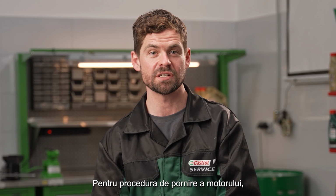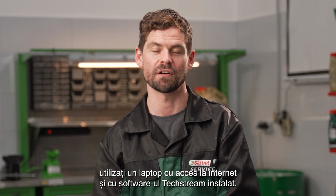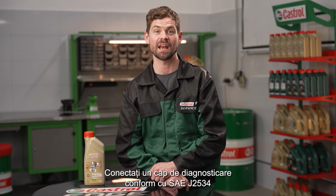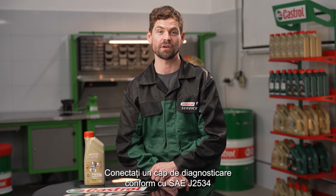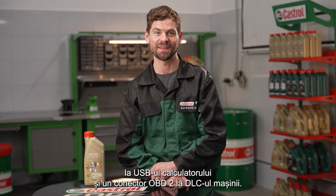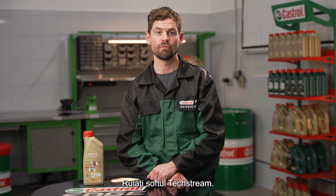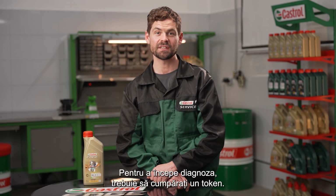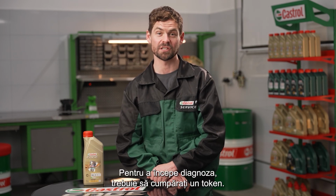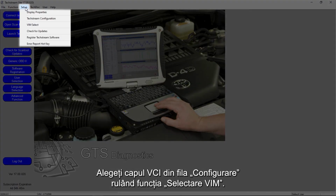To perform the engine start procedure, use a laptop with internet access and TechStream software installed. Connect an SAE J2534 compliant diagnostic head to the USB on the computer and an OBD2 connector to the car's DLC. Run the TechStream software. To start the diagnosis, first you need to buy a token. Start the ignition, select the VCI head from the Setup tab by running the VCI Select function.